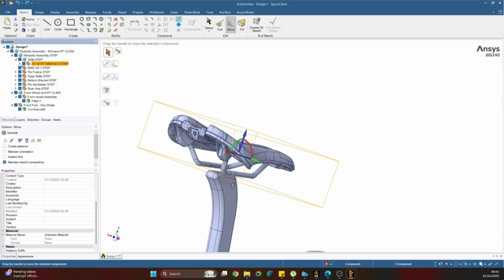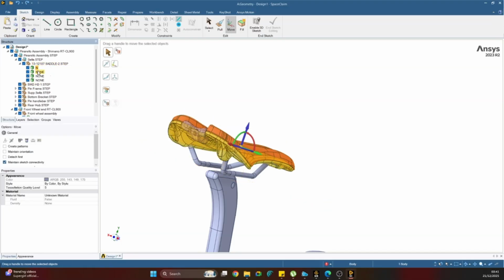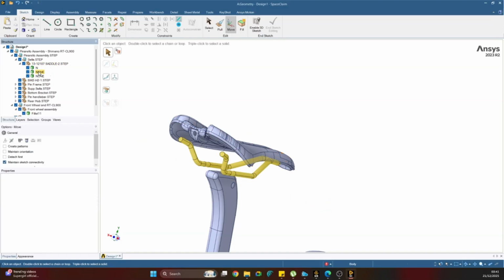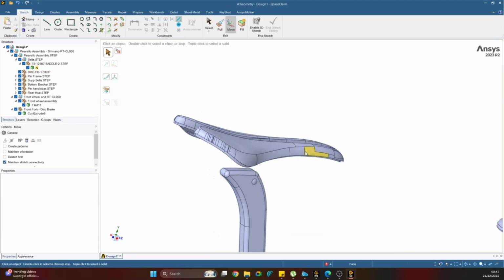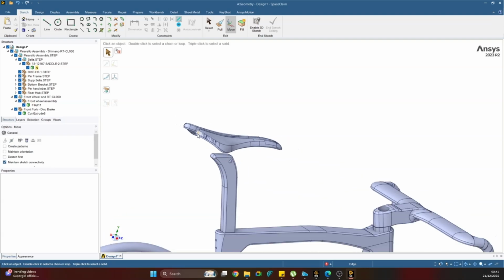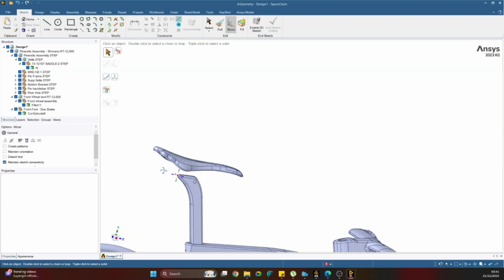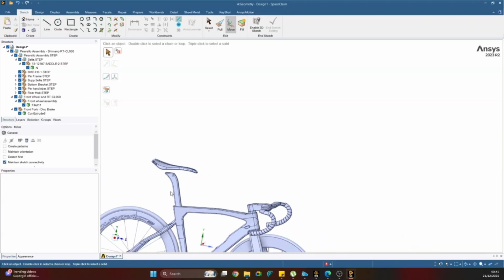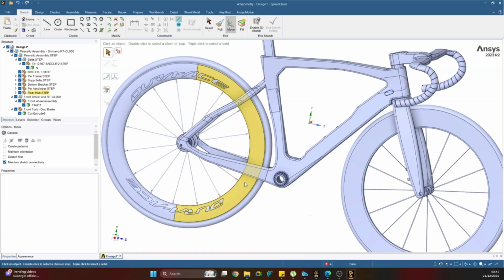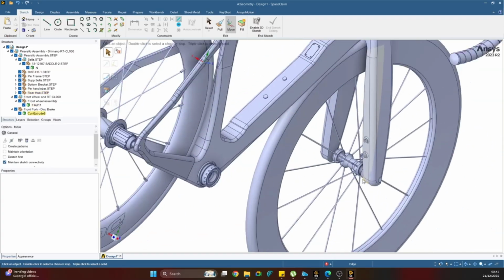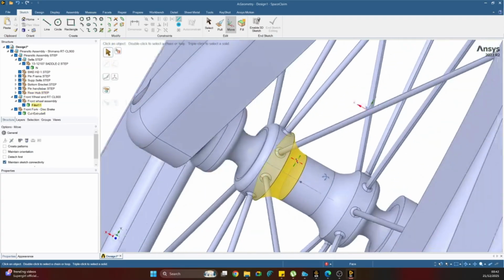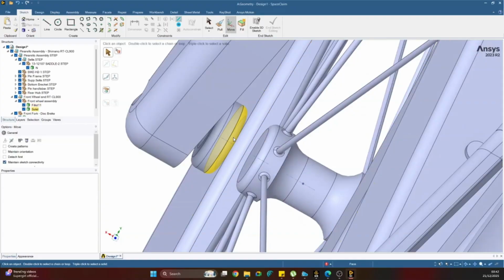Okay, so let's see what's inside this solid. Upper surface is important. We will remove the lower surface. We don't want this. We don't want this. You can have the complete geometry, but again, if you get any meshing problem, then you need to use your expertise in meshing in order to resolve the problems. So this is the reason I'm removing the things that might create a problem.